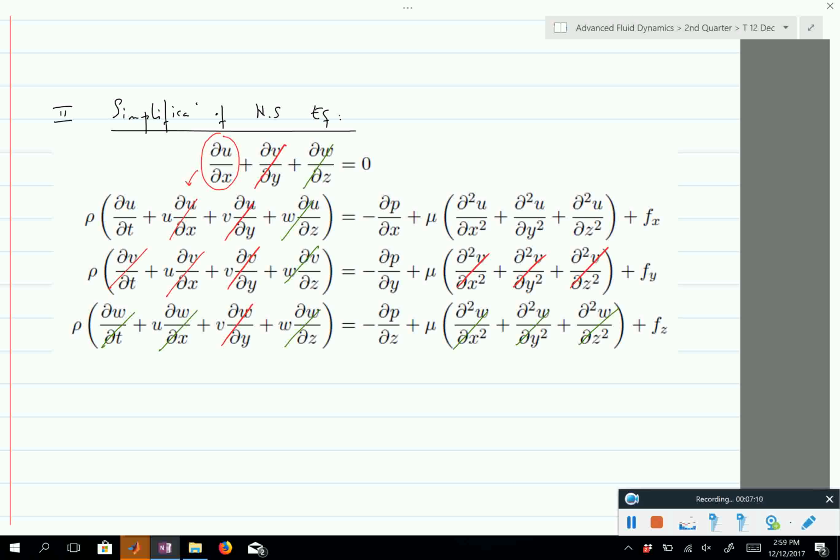You can no longer accelerate in a straight line, you can no longer change the direction of the flow, so there is no more effects of inertia. So here, from the equations, when you have unidirectional flows, then there is no effect of inertia. That has to do with the flow geometry. Your Reynolds number may not be small. It may not be equal to 0 or 0.01, right?